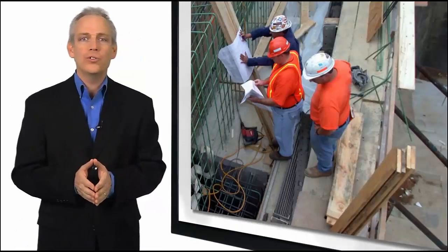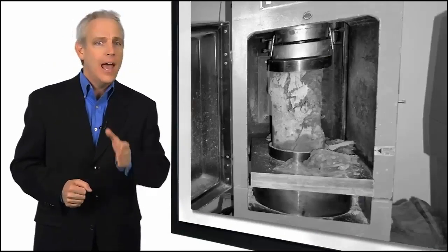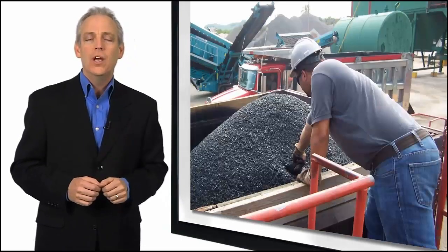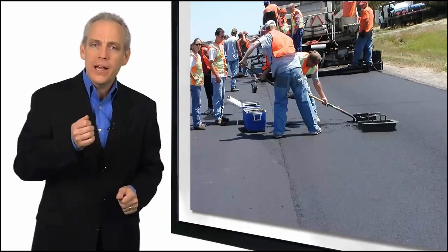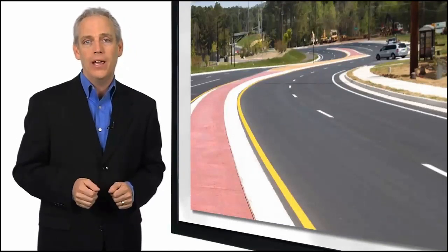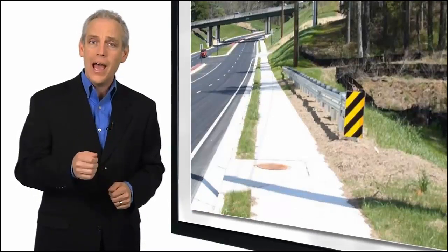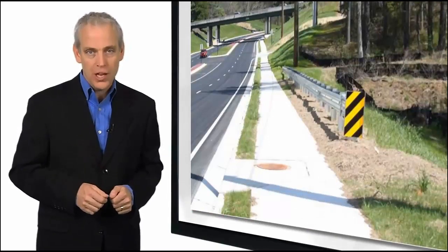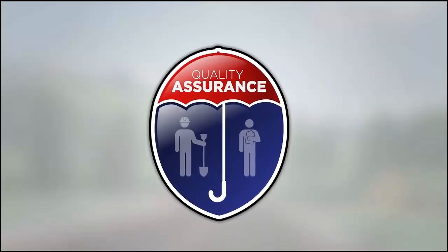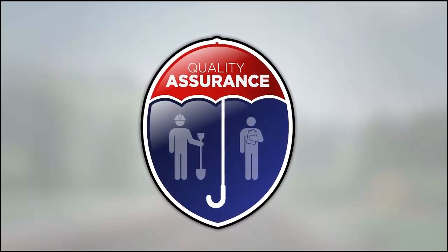In doing so, it's important to know the principles of QA and its requirements for federal aid construction contracts and how a local public agency, or LPA, can comply with these requirements. QA for highway construction is built on key principles that have been developed and accepted nationally by the FHWA, the American Association of State Highway and Transportation Officials, or AASHTO, and construction industry organizations. QA is a broad umbrella term covering the shared responsibilities of both the contractor and the agency for achieving a project's contracted level of quality.